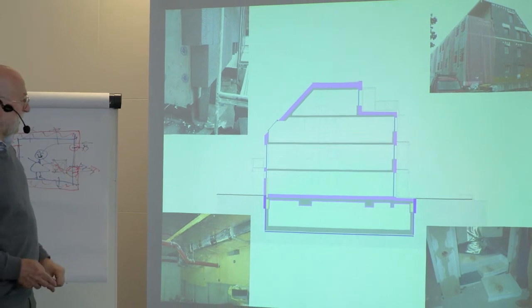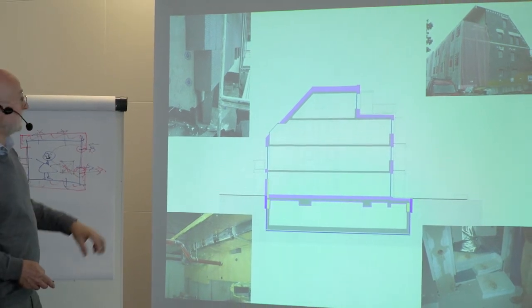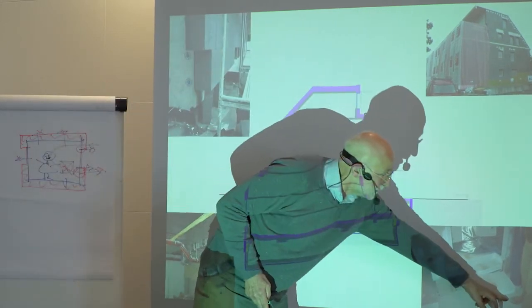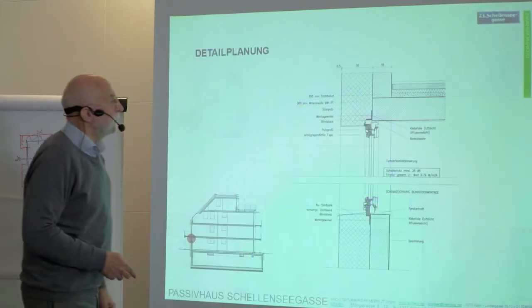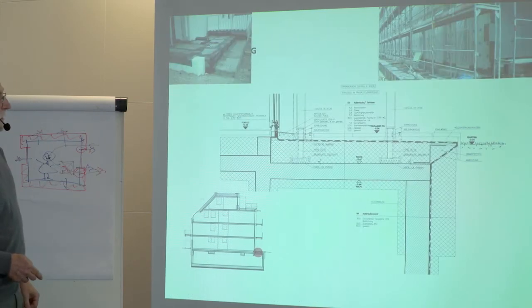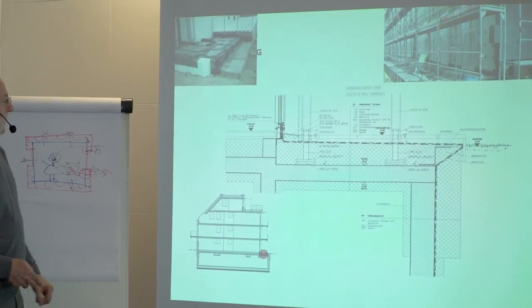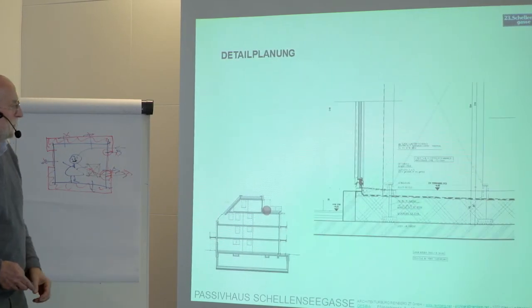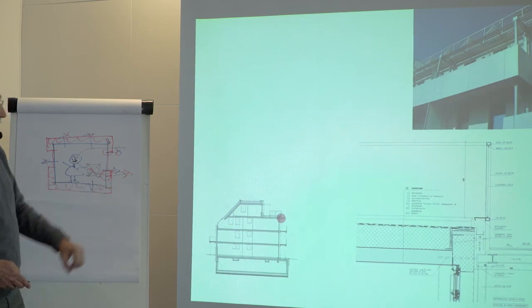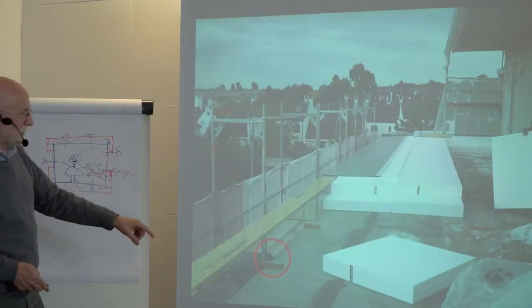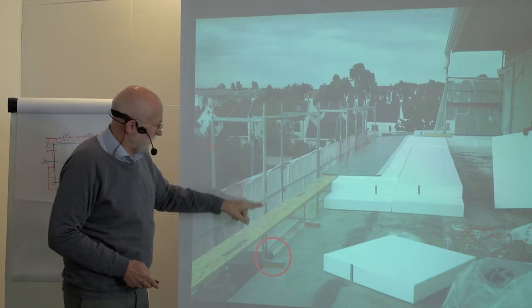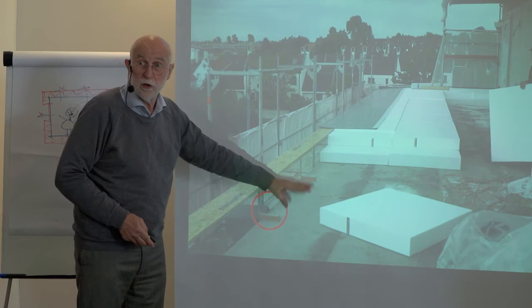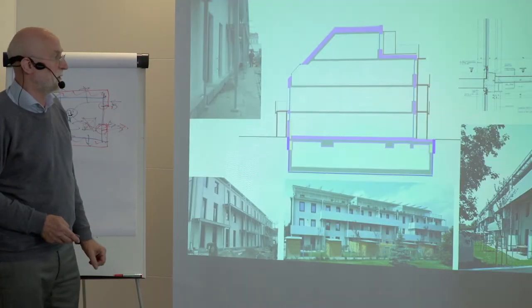We have very heavy insulation, up to 40 centimeters in this case. It's on the wall here or on the roof here. So this is my shoe. A lot of detailing. In my belief, the architect should also get a little more honorarium for all this work, because all these things have to be detailed. For example, the fence is fixed here, and all the metallic parts are separated from the concrete to have no thermal breaches.